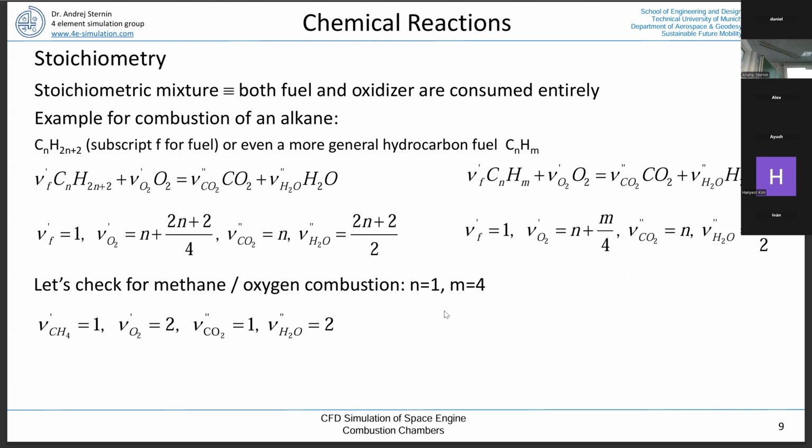This holds for most of the combustion. However, if we go to very high pressure, then Mother Nature kicks in and says, okay, at very high temperature, we are not following this global reaction scheme anymore, because at very high temperature, we are starting to decompose the product water into hydrogen, oxygen, radicals, even generating electrons because of the very high temperature and very high energy.